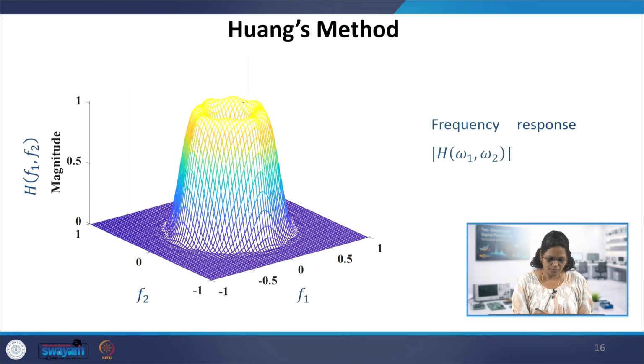So you can see the response for less than 0.1 and between 0.1 to 0.5, we have this band of frequencies, and then it is going to be the stop band here. These are the stop bands, circularly symmetric, and the ripples are very small over here. You can see the ripple of the Hanning window, which gives very low ripple. This is obtained using the window method, the first method we had learned: giving the 1D window and using that 1D window for designing this 2D FIR filter.